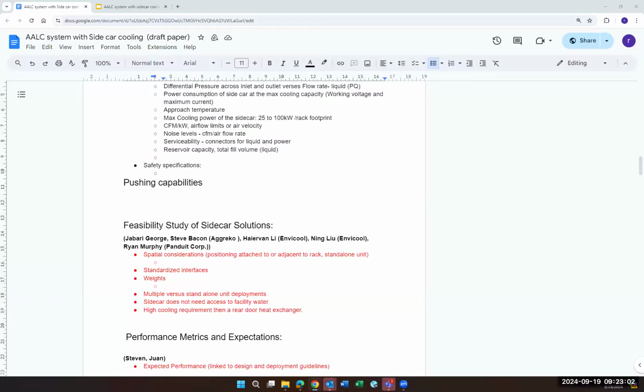In my opinion, it's a critical component in data center applications, because if the safety valve opens or any leakage happens in the product, then the liquid will flood and make the data center components stop working. It's a high critical and safety issue for data center applications. Which means that if you build a safety valve, you must know where the extra liquid will go in the case of high pressure.